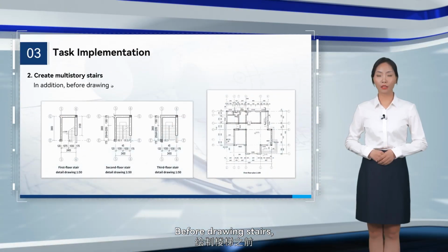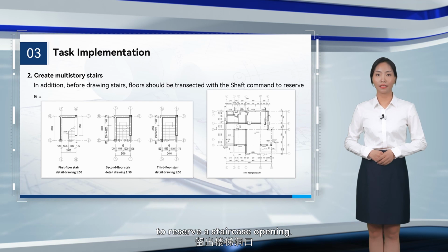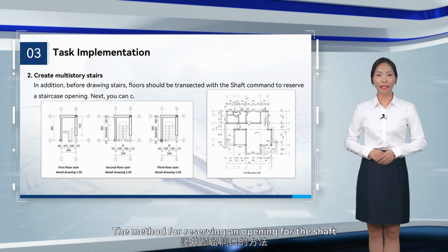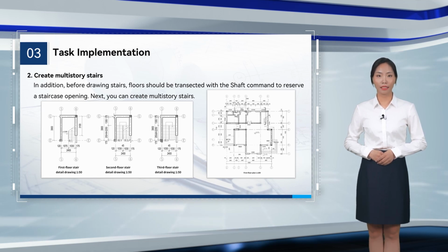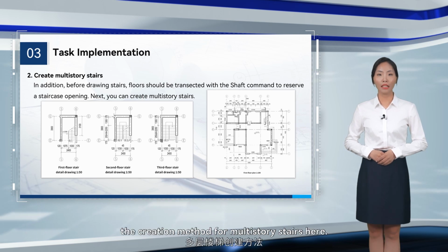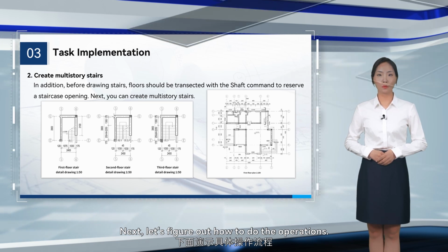Before drawing stairs, floors should be transected with the shaft command to reserve a staircase opening. The method for reserving an opening for the shaft is covered in the previous chapters. I won't repeat it here. I will only present you the creation method for multi-story stairs here. Next, let's figure out how to do the operations.